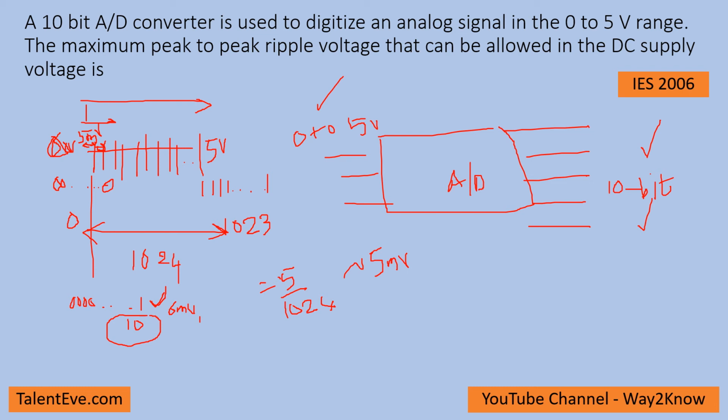So just to explain again, the ripple voltage is nothing but, let us assume there is a DC supply of 5 volts. Generally there will be some AC noise introduced onto this. So in reality, when you capture the signal in an oscilloscope, it looks this way.